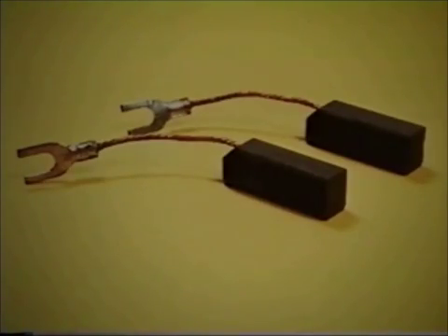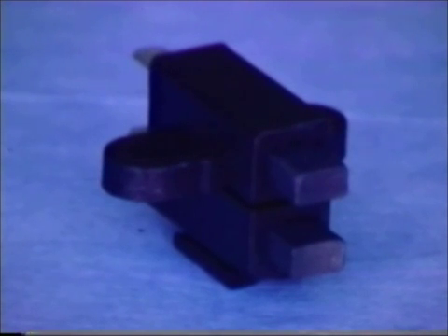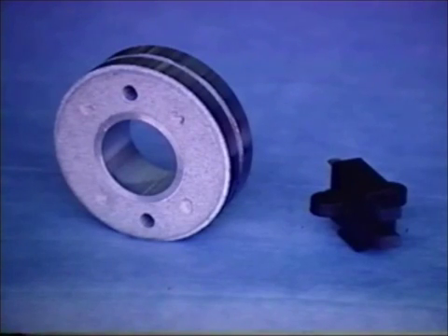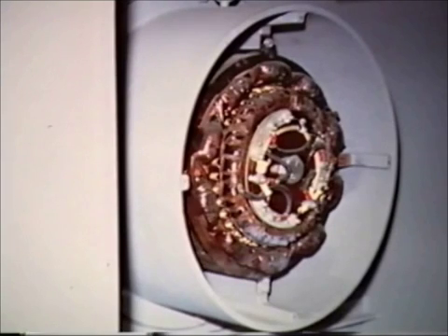A conducting element constructed of carbon, graphite, or in some cases copper, is called a brush. The brush is used to maintain a sliding electrical contact between stationary and rotating components. Brush holders are devices used to house and support a brush or brushes. Collector rings or slip rings are rings usually constructed of copper, on which the brushes slide to provide electrical continuity between stationary and rotating components. An exciter is a device used to supply DC current, excitation, to the field winding of an alternator.